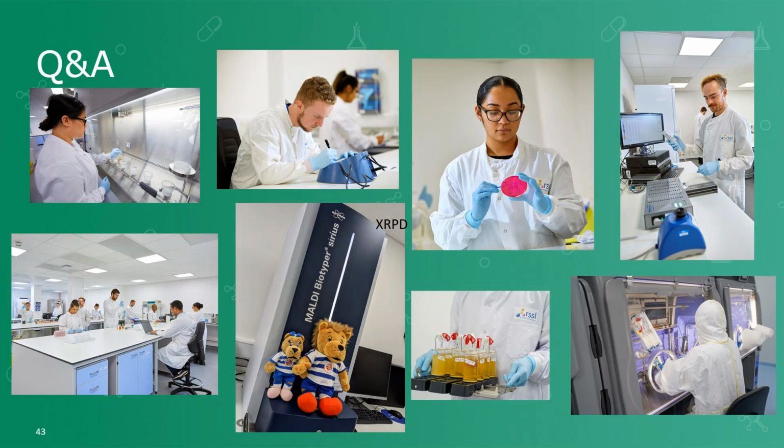But on this particular subloop, the appropriate valve wasn't turned, and that part of the water subloop remained at ambient temperature and gave an opportunity for microbial growth, and again the release of endotoxin. So these were both WFI systems, but they're both post-distillation. So the stills were working fine. It was events subsequent to that that led to these contamination events.